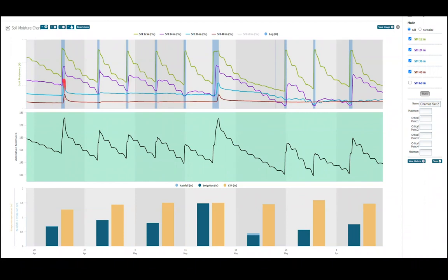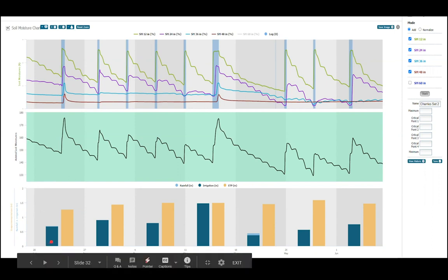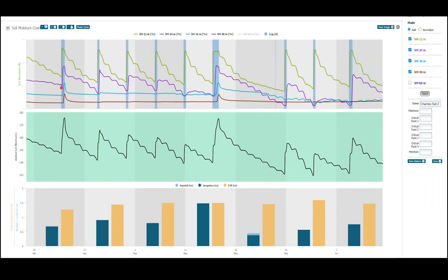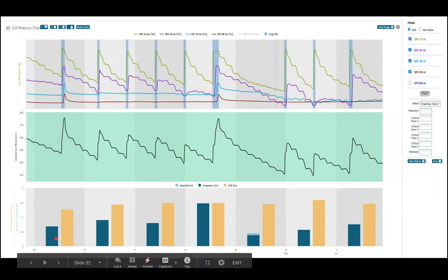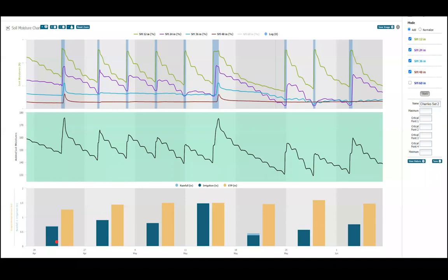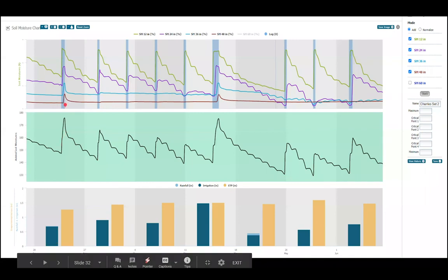It was one event during the week in gray here. The different grays show the different weeks. This is the week of April 20 this year, April 27, May 4th. So we can see this grower did a long irrigation, one event during the week. He put out half an inch on one event. So the water got all the way down, or more, it was more like 0.65 inches. And the water got all the way down to the 4th foot.